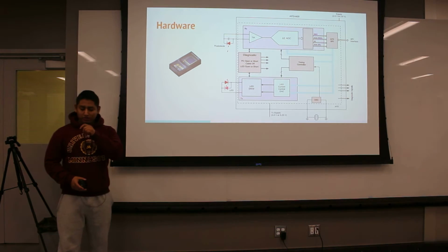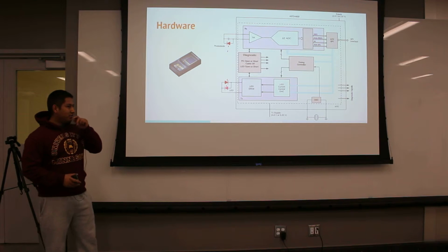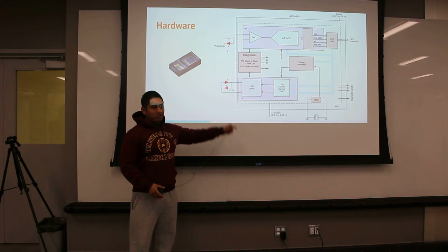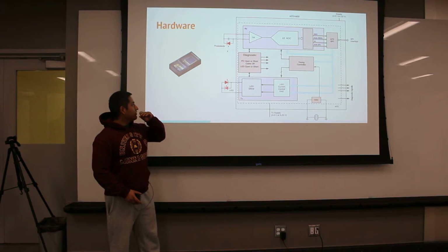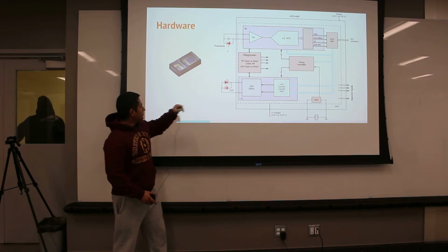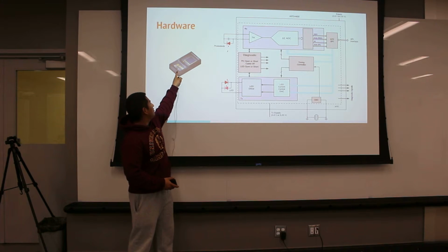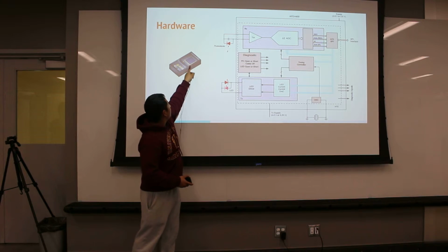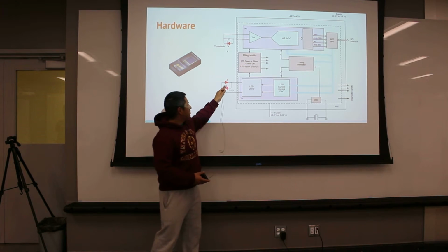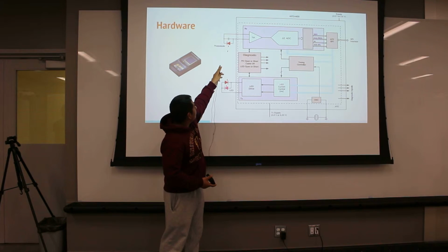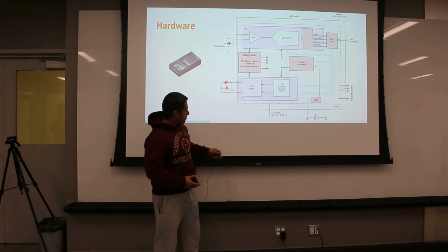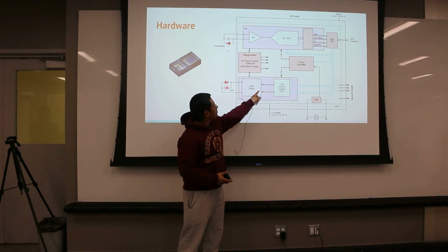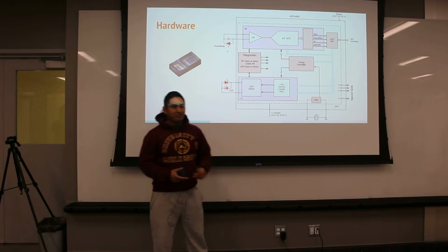So these are the components we're using aside from the PSoC. We have the AFE4400, which has everything. We just attach this guy, the Bioman sensor. It has LEDs here, and it has a photodiode here, which has a schematic in the AFE4400 documentation. And we just supply 3.3 volts to this AFE, and that should just work fine.